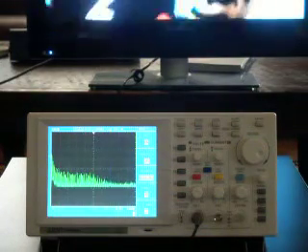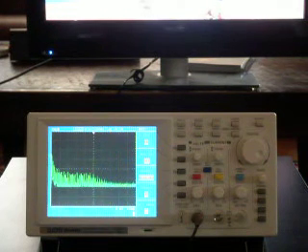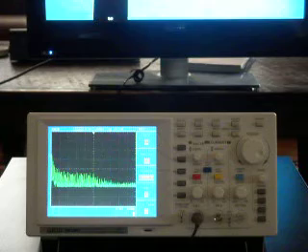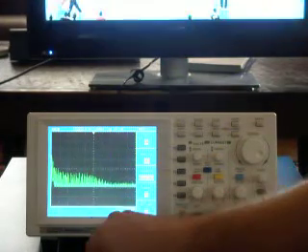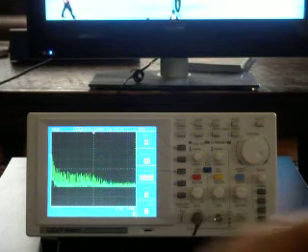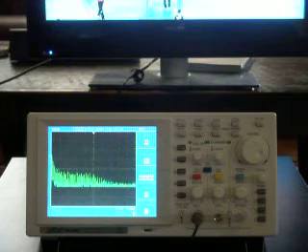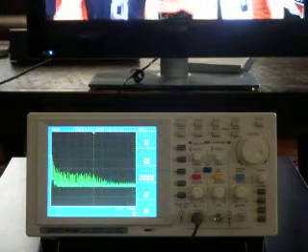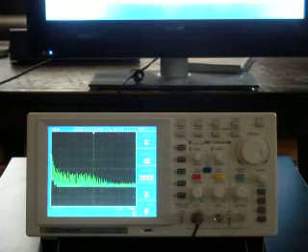And I've gone around my products and I've actually identified the products that produce these really bad harmonics. And you can detect this with an AM radio just simply by tuning it into static and putting it near to the electrical cable, and you'll hear the radio buzzing in line with how much harmonics is on that cable. And I have separate videos that show that effect, particularly relating to this television.